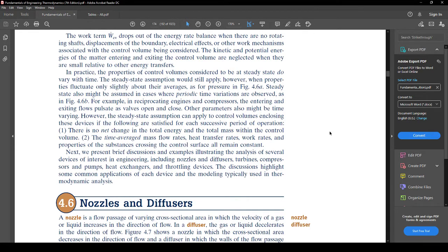Will you have any non-steady state problems in this course? No. Fairly certain, no. Let's put it this way: there will never be a time where, if you have one inlet and one outlet, your mass flow rates will not be the same. But obviously, if there are two inlets and one outlet, your mass flow rates of 1 and 2 have to add up to 3, and so your mass flow rate of 1 does not equal 3. You see what I'm saying? Essentially, if it's one inlet, one outlet, they will be the same in this course and the next course as well. So it should be easier for you.